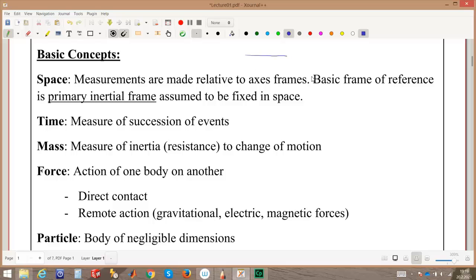However, if you have ever slid a door, you can imagine that it can move up and down a little bit, so the constraint is not that fixed. It doesn't really move on a straight line, but it might have a motion something like that. It can move up and down, but it's very limited. Nevertheless, it can move up and down because there is a clearance. You need to have clearance between this rail and the door itself.